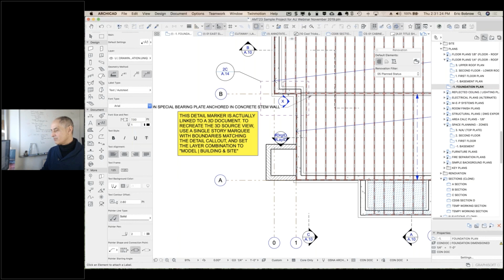No, you cannot do a vertical complex profile, because a complex profile is basically an extrusion of a section. This is true for walls, and it's true for beams. Like you can have a beam that's a piece of steel, so it's got a shape like an H or a C-shape steel. Now you can do columns, so you can make something vertical. It's a column that's a piece of steel, or steel with veneer, various things like that. But you can't say, as I move along the wall, repeat the cladding gaps. So it's unfortunately not available.